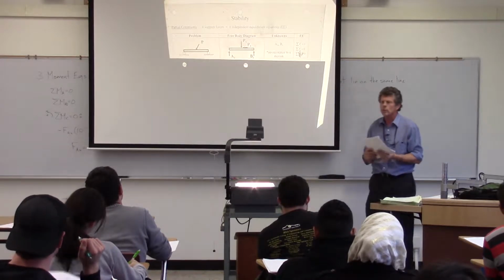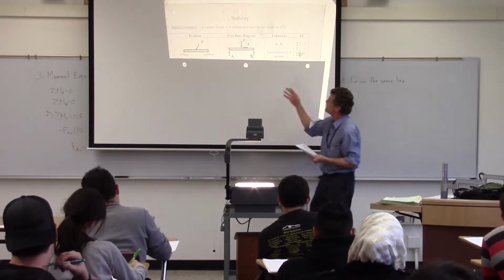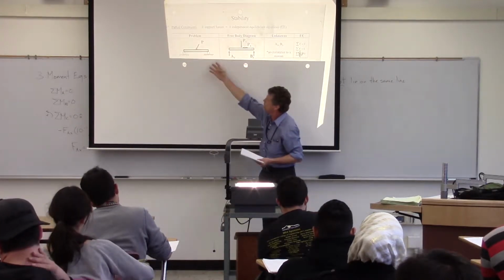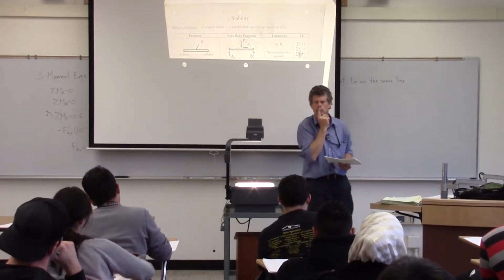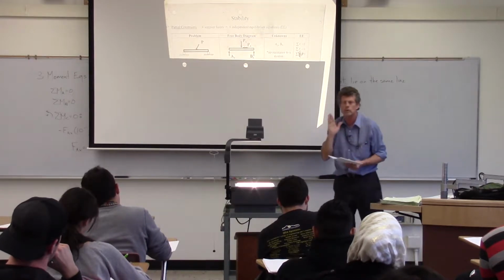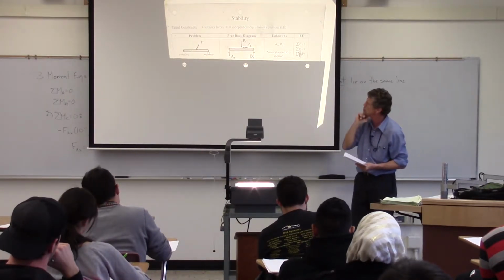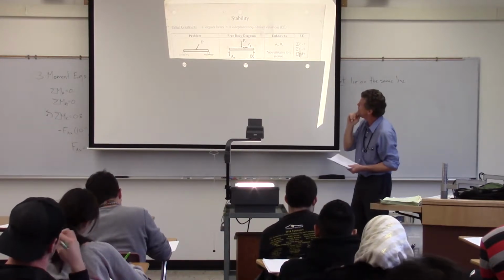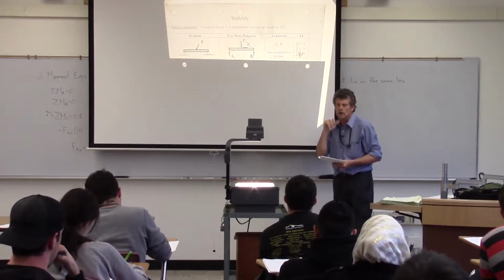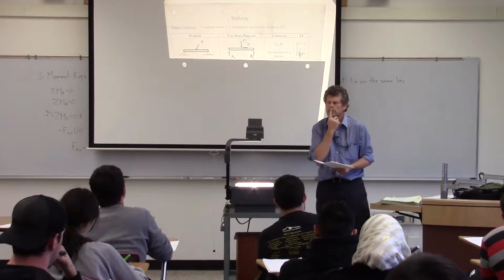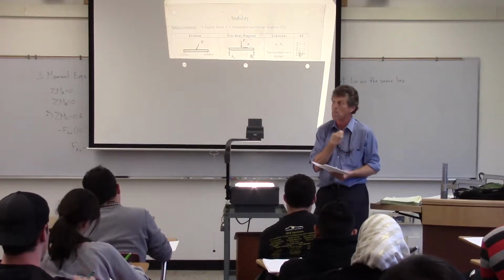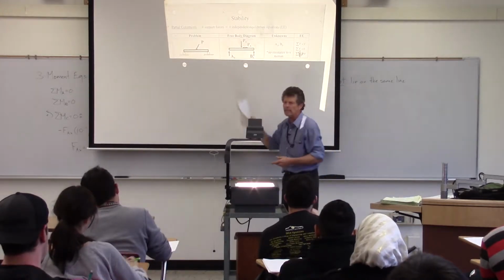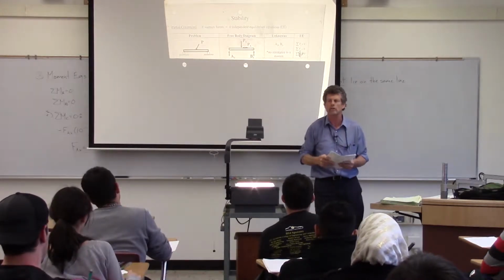So there are situations, again, when the key thing, and this is why we say the free body diagram is so important. Draw that free body diagram. There's my supports, 2 rollers. Well, then that means I've got forces vertical or perpendicular to those surfaces. I end up having 2 parallel supports there. But again, if I have a load that has any sort of x component, think about the sum of forces in the x direction. Nothing there. I've got px, but I don't have any support to resist that.